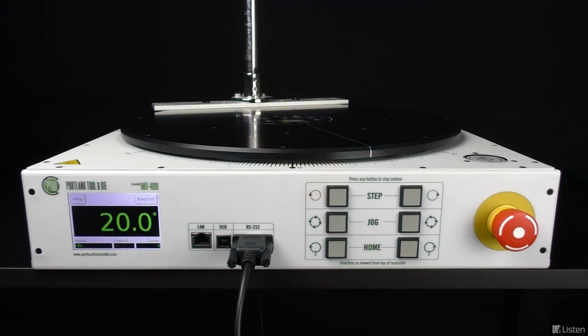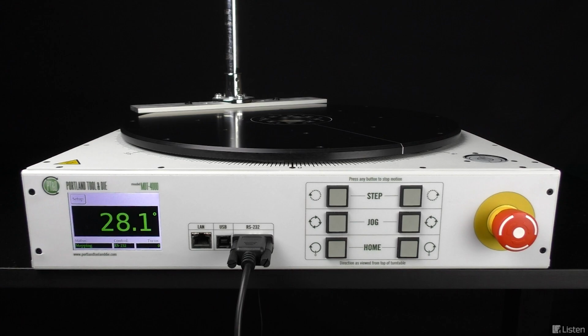Sequence looping is a useful technique that saves both sequence writing time and test time by running repetitive test elements in a loop within a sequence. This is valuable for any kind of test where you need to repeatedly change a test parameter. For example, increasing stimulus level by 5 dB to retest, making measurements in multiple fixed frequencies or frequency sweeps, or even moving a turntable and remeasuring a device to create polar plots.